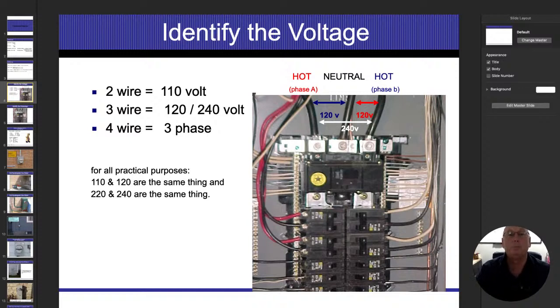And if we look at the picture in the diagram, the middle wire of those 3 wires, that's my neutral. That's my 0. So if we take the energized conductor on the left-hand side, that's going to be at 120 volts. If I measure between the neutral and that energized conductor, I'm going to get that 120 volts. If I measure the same thing on the right side, between the neutral and the energized conductor, that's still going to be 120 volts. And then when I measure between the 2 energized conductors, this is where I get the 240 volts. One will be positive 120, and with alternating current, it's always going to change from positive 120 to negative 120. Positive 120, negative 120.